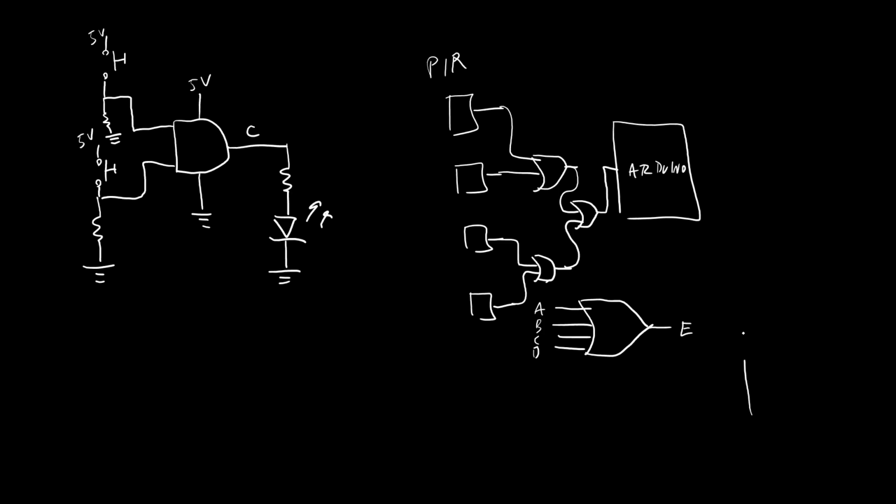When you physically go buy these, they are usually going to come in an integrated circuit package, so you'll need to look up the datasheet for what the pinout of that package is. For example, there's usually going to be a ground connection and a power connection, and then it'll show you, for example, for an AND gate, that these two inputs are wired like that, and then the output is like that. So you have inputs A, B, and output C, but then the integrated circuit is usually going to have more than one, or many times have more than one gate in a single package. So again, depending on which gate you need, go look up what you actually buy, and then look up the pinout of the integrated circuit to figure out how to physically wire it on a breadboard.